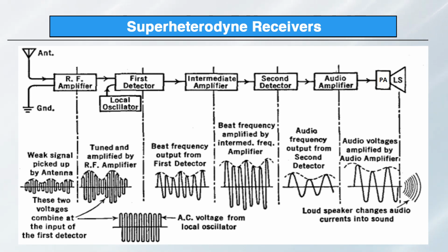The characteristic of this component is that it operates in the audio frequency range of 20 Hz to 20 kHz with a linear response to faithfully reproduce the audio signal, and may consist of one or more stages of amplification to achieve the desired output level. The design considerations are that it must ensure low distortion and high fidelity to accurately reproduce the original audio signal. Impedance matching with the output transducer, speaker or headphone, is crucial for efficient power transfer.